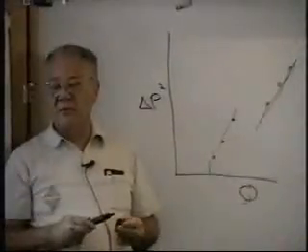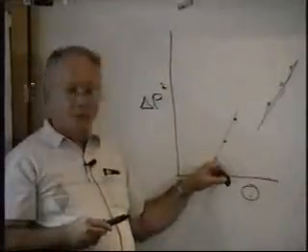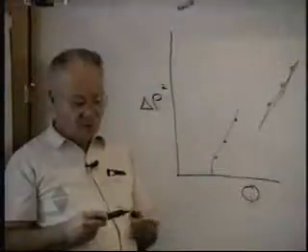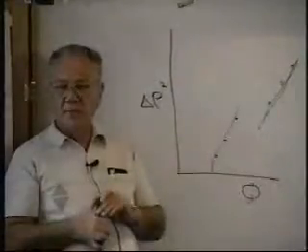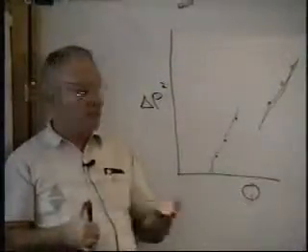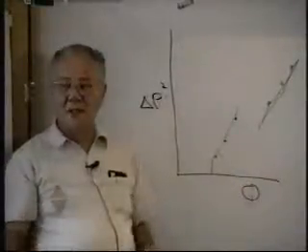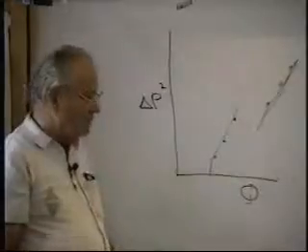Up until then it was backflowing, so you actually had a negative. You could add an additional Q to this because a part was flowing backwards into the other layer. Once I finally got the flowing pressure below the shut-in pressure, then you had a big shift, and I had Qs from both layers now, and there wasn't any negative flow, any backflow.